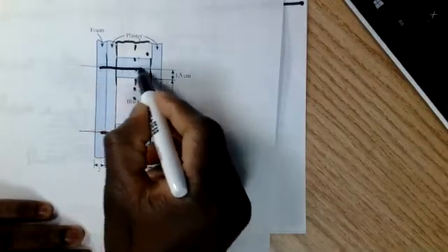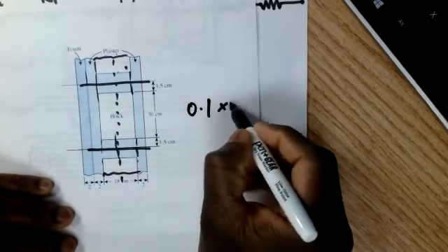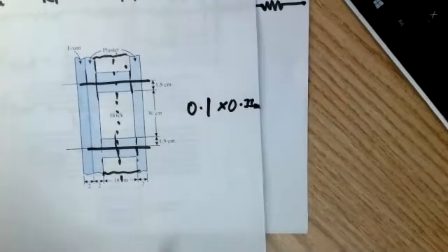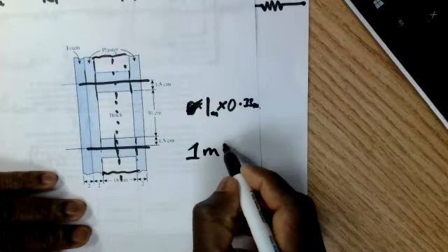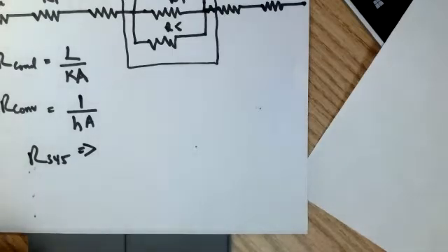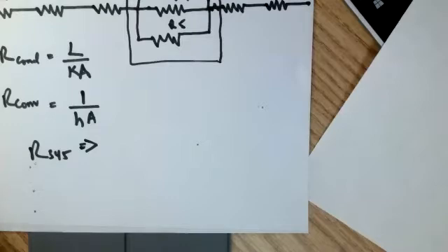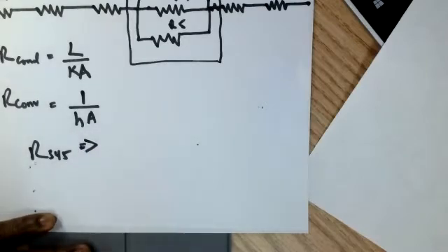Now, this portion that I have coded out to do the analysis with is equivalent to a 1 meter by 0.33 meters wide portion of the wall. Okay, sorry, 1 meter by 0.33 meters. Now, if you pick 1 meter by 0.33 meters and you evaluate it, you get a ratio. It's the same ratio that applies if you consider the entire wall. Okay, if we count the number of bricks, you will have an entire 6 meter by 4 meter wall, and divided by these areas and thermal resistances, you get the same ratio.